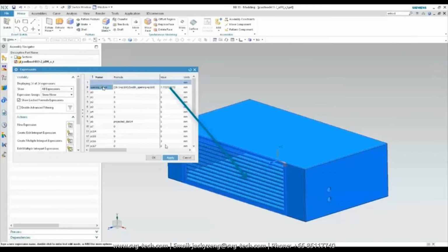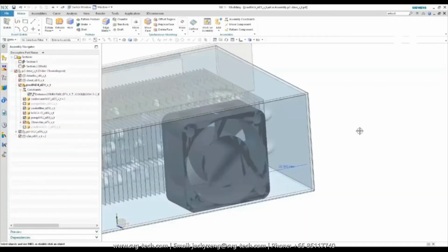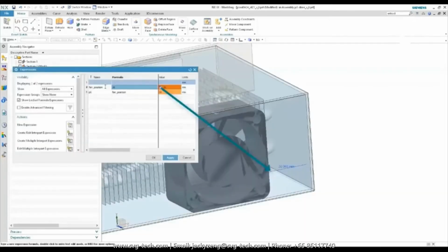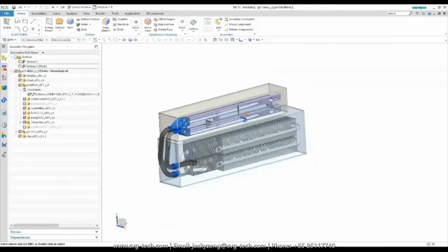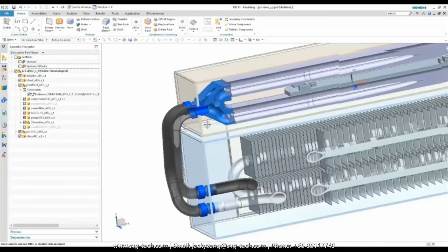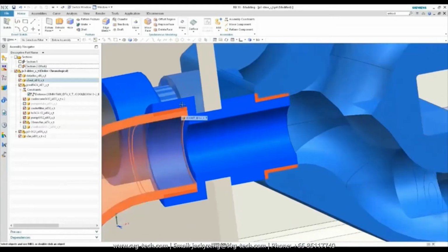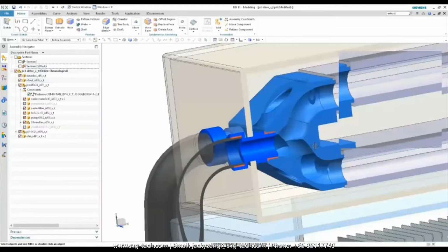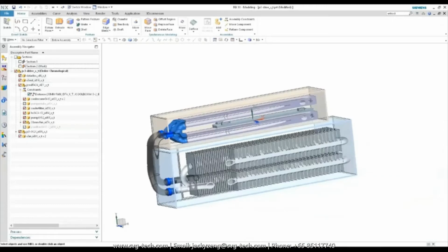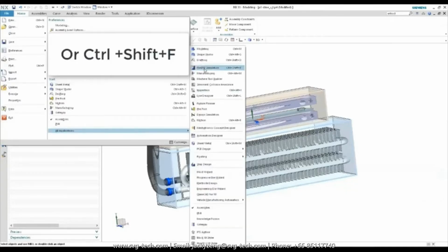And the last thing that we'll parameterize is the placement of this fan using an NX constraint. What I'm showing you here is a cross-section through the geometry, and as you can see, the parts highlighted in red are intersecting. FlowEFD can easily handle intersecting geometry using material priorities. So that's just some of what FlowEFD can do.